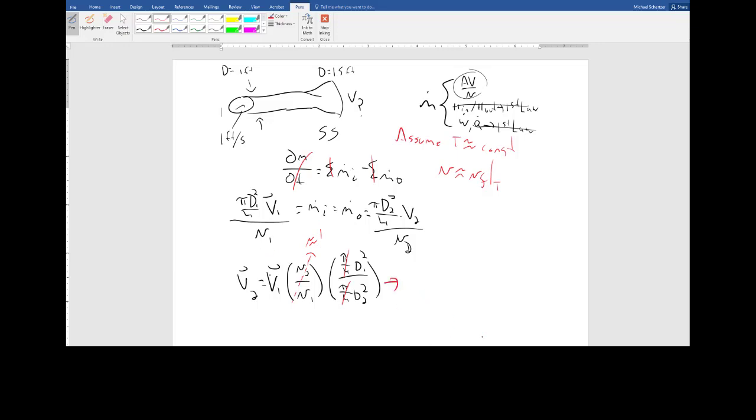Especially for liquid water, the density of water is always about 1,000 kilograms per meter cubed, or the specific volume is always about 1 over 1,000 meters cubed per kilogram. So it's probably not a terrible assumption to say that this is about 1, unless you get a really big temperature change or you start to boil. If it was liquid to liquid, but it says it's incompressible on both sides, I think, right? Yes, just say the same liquid.